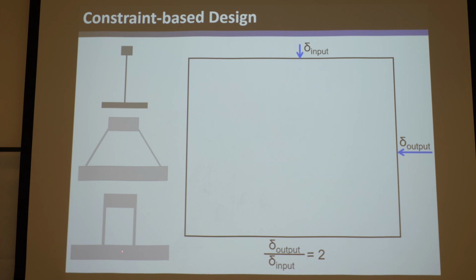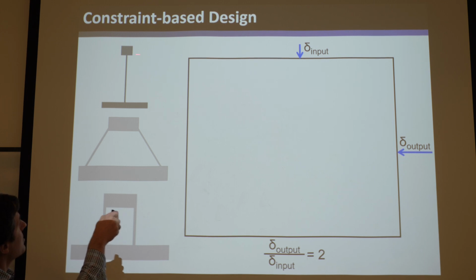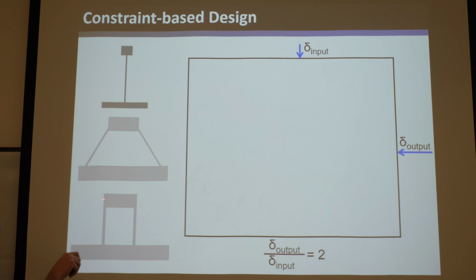Well, say you just had these building blocks to work with. These are some of the most common, and you can visualize how they move. This has an instant center where they intersect, so it gets a rotation. This gets rotations and translations, and this just gets a translation, right? So knowing this gets a pure rotation, then it gets a pure translation. Even though for large deformations this arcs and the axis of rotation actually drifts, let's just simplify things because it's tough to visualize all that.